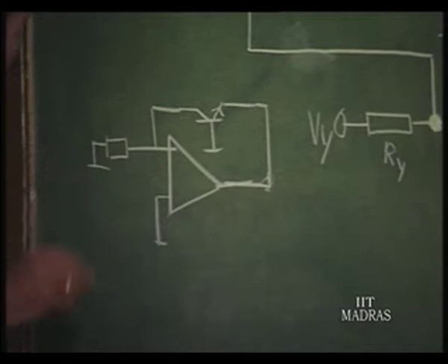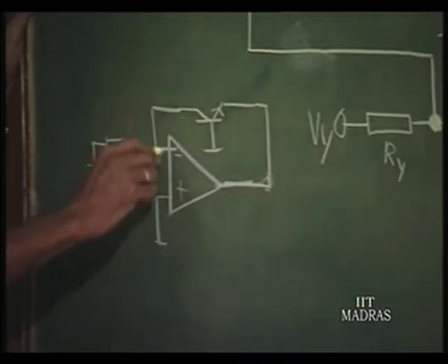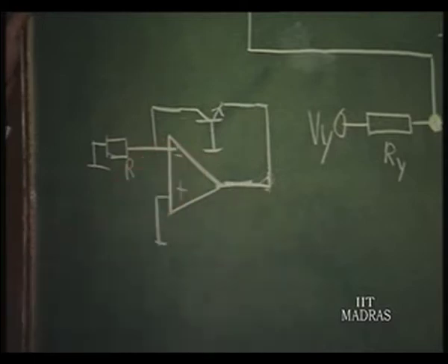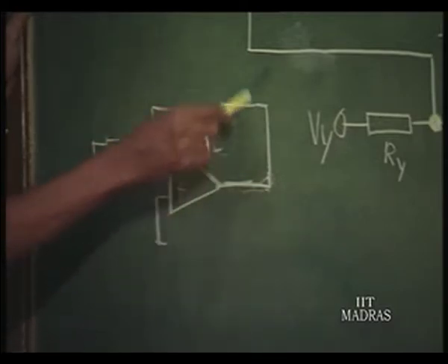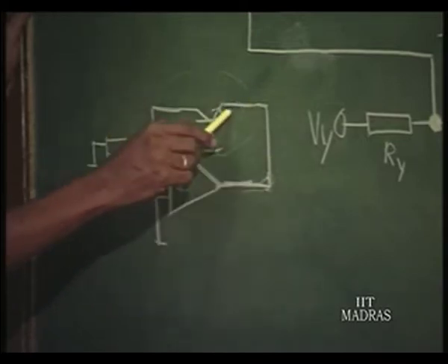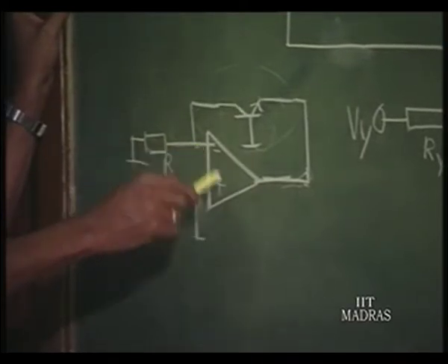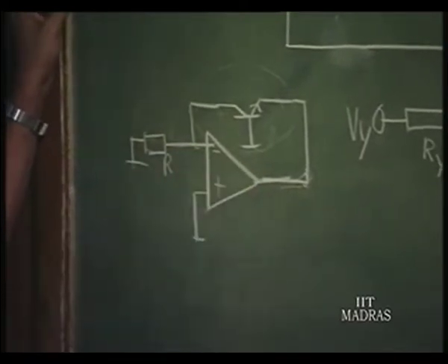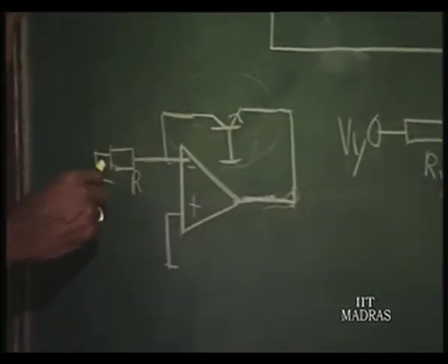If you consider this as a feedback circuit, the original amplifier was getting fed back from this point, unity gain feedback. Now, you are putting output of this to an amplifier here. This is nothing but a common base amplifier. This is fed to the emitter, and at the collector load you are taking the output. So, it is not a simple op amp, it is an op amp with active feedback.